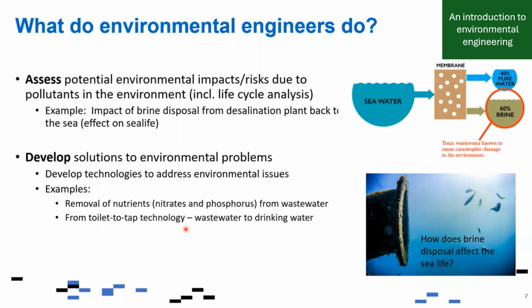We can do it as direct potable reuse. It means that we don't put the treated water in a reservoir for a long time anymore. It's direct. You can just easily drink it, which is safe. But you can also have an indirect potable reuse, in which you treat the wastewater, put it in a reservoir for some time, and then go through a water treatment process again, and then you can drink the water, which is mostly the case. But we engineers, environmental engineers, civil engineers can work on these processes, and we have the technology now.